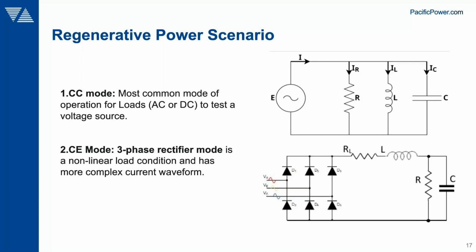And then we'll run another, more sophisticated example of a rectified type load condition where we will simulate a typical inrush current that occurs when you turn on a load for the first time and the input rectifier capacitors are uncharged. So there will be a surge current that goes in initially that will then decay. And we'll show you how you can easily set up these kinds of load conditions on the electronic load using the circuit emulation mode.